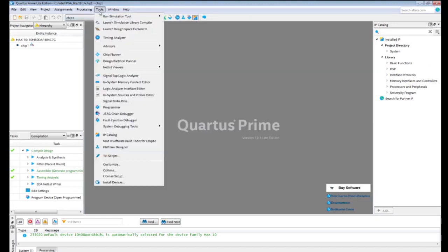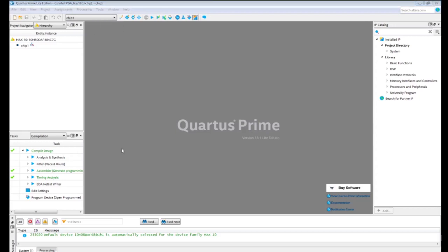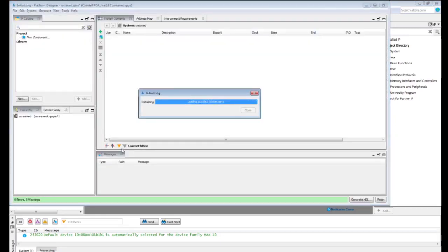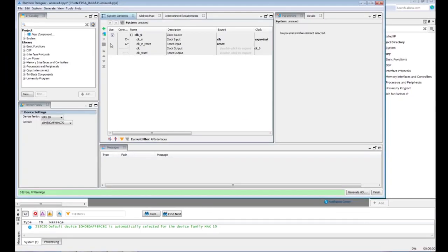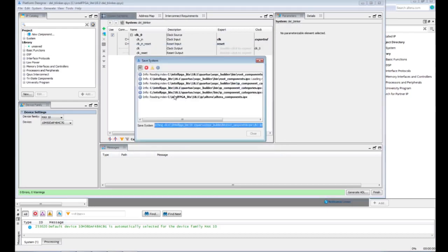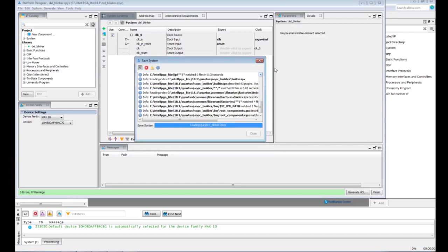The program generates the code itself, and then we will upload it on the board and program the board, write our code, and then light up the 2 LEDs via the switch. We will start by having the clock, the main clock. It's already there. We will rename it to clock_main. And then from the IP catalog, we will start adding our components.